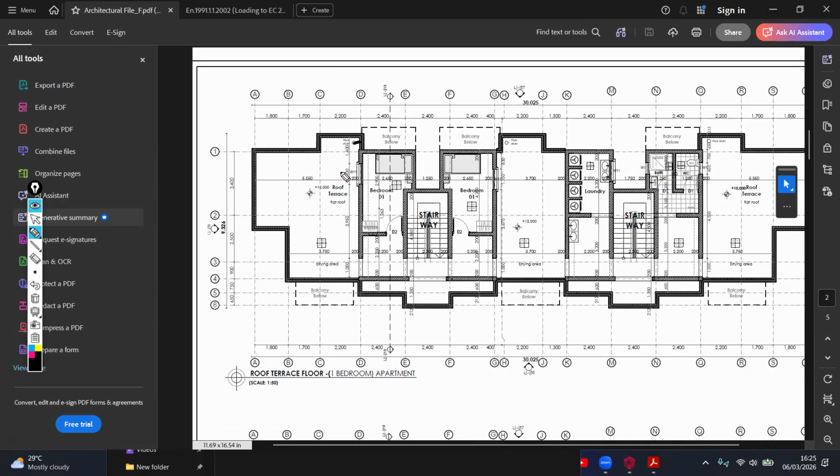Now, remember, we have up to fifth. So at fifth, that's where we shall have the ring beams for part of the structure. Remember, not all the structure has a roof. Parts of the structure are roofed, like, for example, here. Only this part is where you shall have the roof, where you shall now have ring beams on the fifth floor.